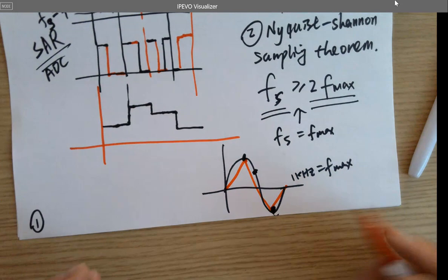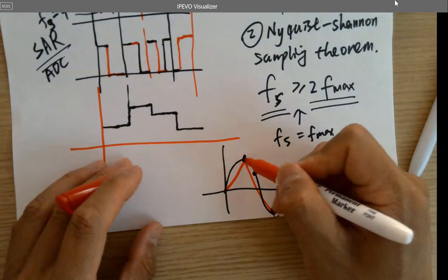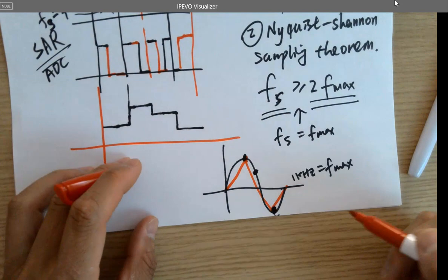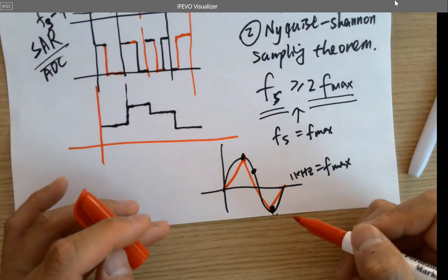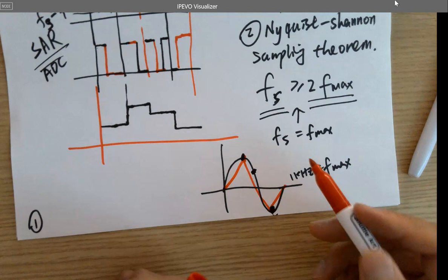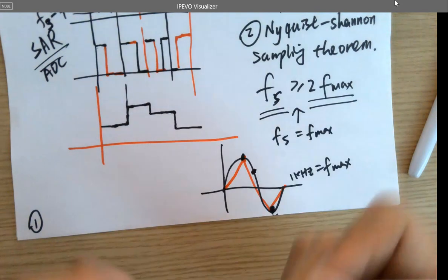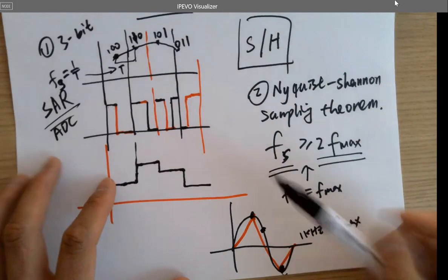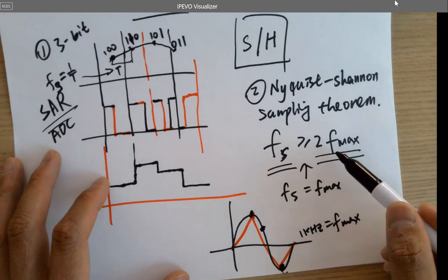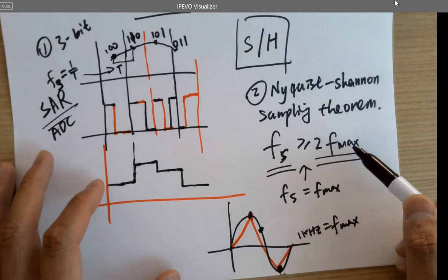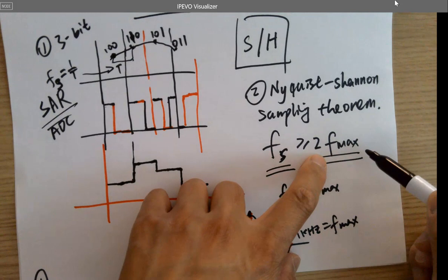Hopefully, I don't know, but still hard. You know that there's a peak, there's a reverse or the negative peak over here, but it's still not ideal. Okay, so when you are designing an ADC, you have to keep in mind that the sampling rate has to be a lot larger than 2 times the Fmax, but we never actually use Fs equals Fmax.